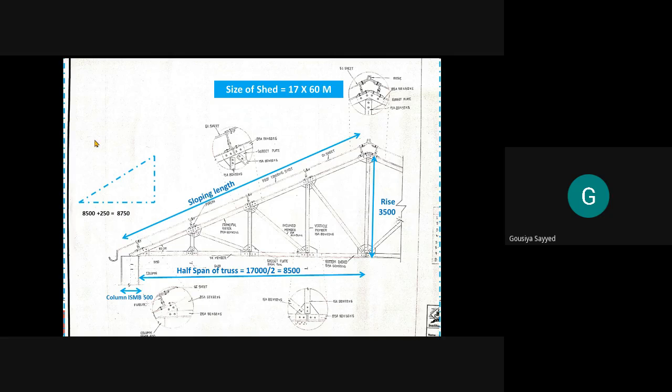In this manner, first you have to draw a triangle, and this triangle is nothing but the center line of all the members which form the truss. Now after drawing the center line, let us show the members of the truss.